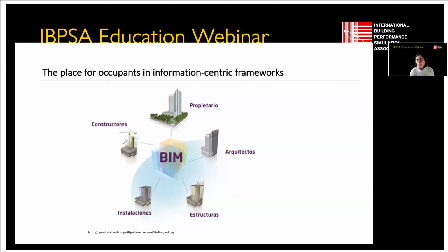And what exactly are these objects? They are packages of information, for example, of construction assemblages, of room usage, etc., that are manipulated by different members of a design team in a BIM environment. These objects can, in theory, contain any kind of information and be part of libraries, for example, containing descriptions of repeated simulations, occupancy profiles, design requirements, design aims, decisions, etc. Like other BIM objects, which are stored with all their attributes in different types of BIM libraries.